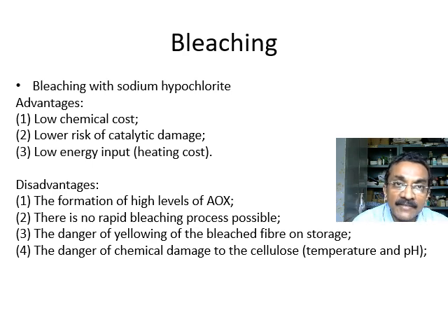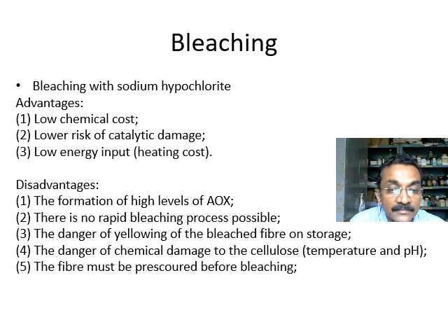At the same time, if the bath temperature increases, then there is a chance of oxycellulose formation. If the pH control is not very specific, 9.5 to 10.5, then also the damage to cellulosic material will be high. So this process is very much controlled at a specific pH and lowest temperature. That is also a major disadvantage, because from the reproducibility point of view, these two things have to be maintained as process control parameters.